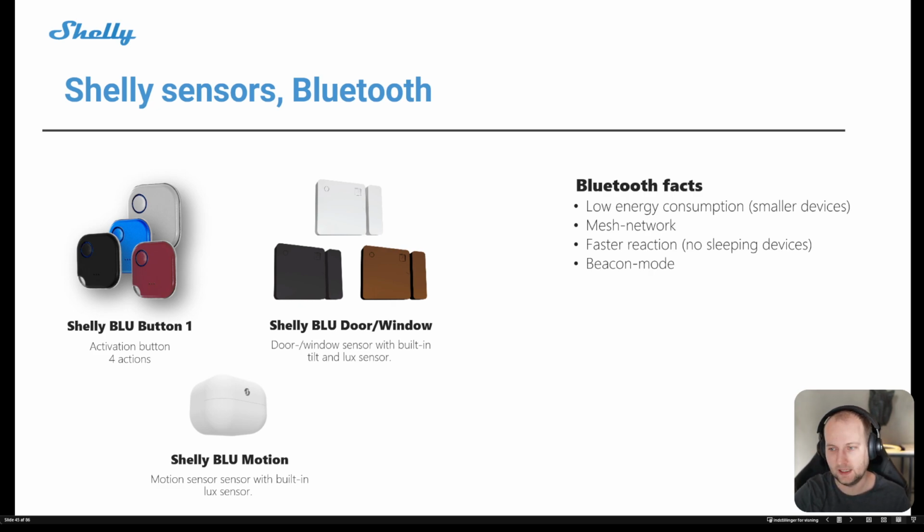The cool thing is that in all Shelly Plus, Pro, and Gen 3 devices, we have built-in Wi-Fi, but we also have built-in Bluetooth. So this Bluetooth device can connect directly to any Shelly Wi-Fi device that has the Bluetooth inside, which means that around your house, you actually have a lot of gateways for Bluetooth. So if you are standing inside your living room and press the device, it will automatically connect to the closest Shelly device where you have enabled your Bluetooth gateway.